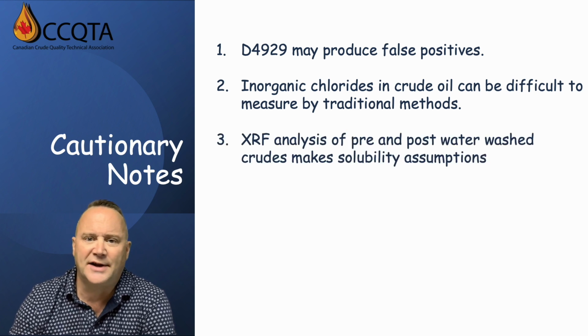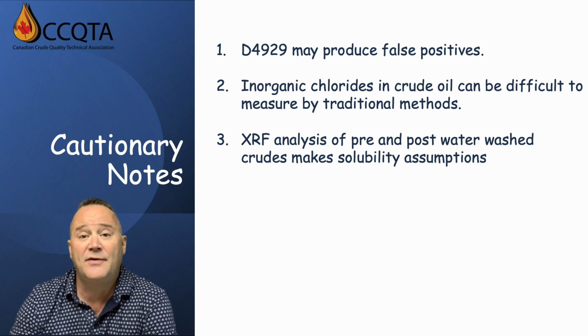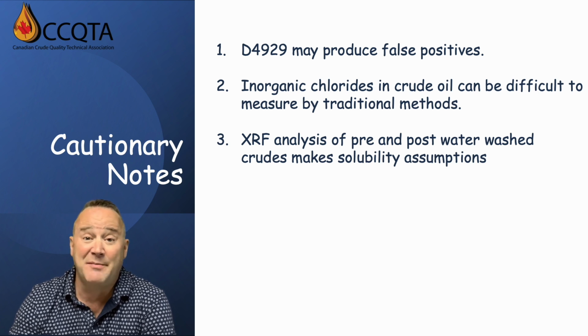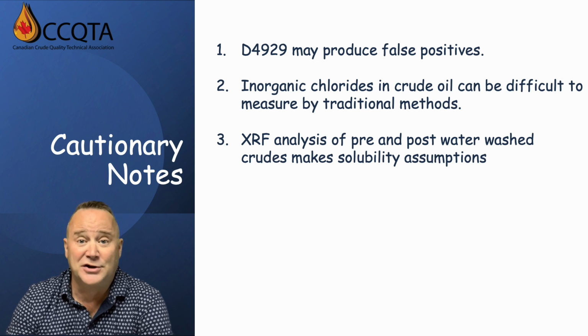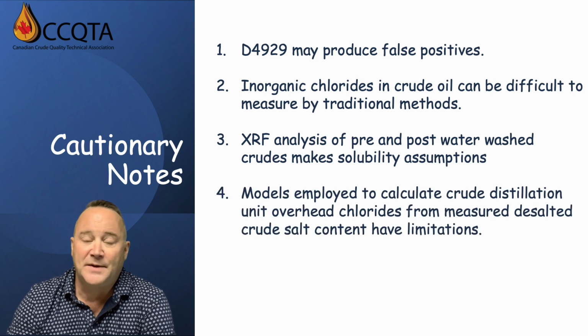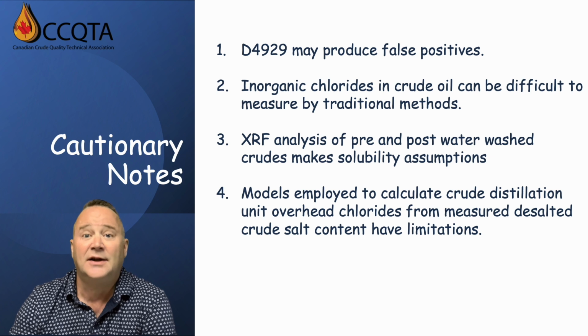Also, differential XRF analysis of a pre- and post-water wash crude assumes that all inorganic chlorides are removed by the water and that those detected by XRF are organic, which may or may not be true, as we've discussed, how chlorides can be masked by other factors, so identification by inference should be taken with a grain of salt. Pun intended.